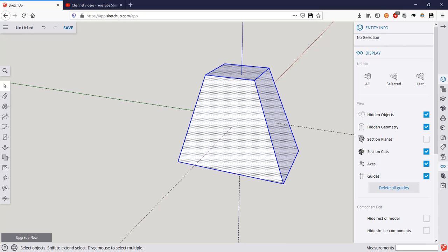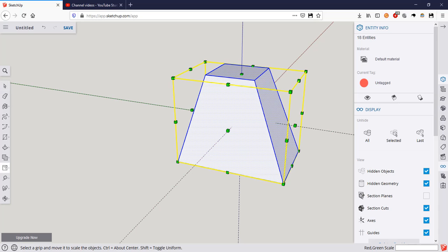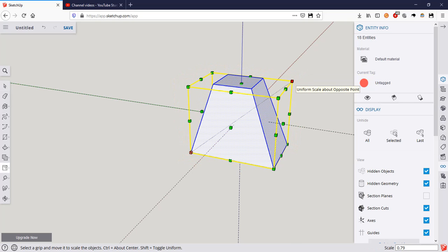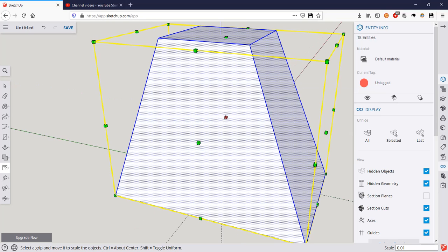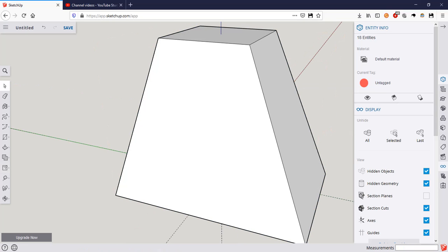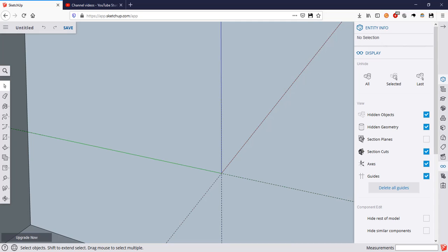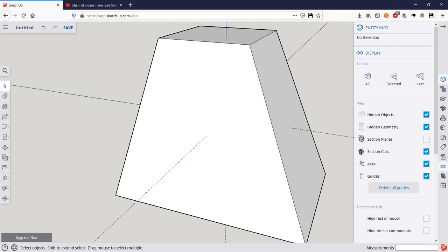But, so you triple click, hit S for scale, Control right in here, and notice it's decimals now, so hundreds is 0. Oh man, what is it? Tens and then hundreds. Okay. Hit enter. Control-Shift-E. And we should be back to 50 meters right here. We are. Okay, but let's say we don't want to do the math.